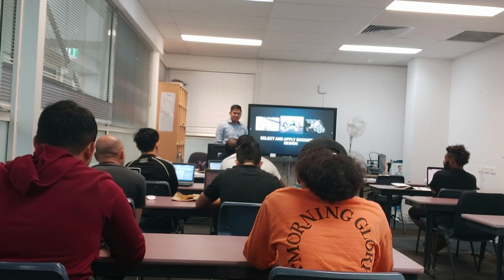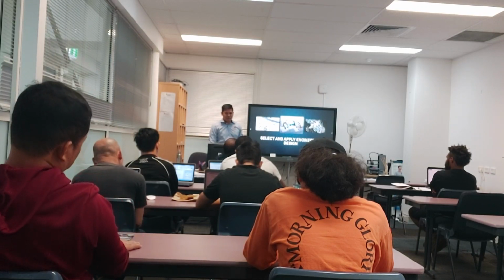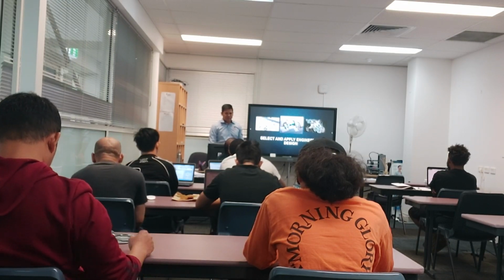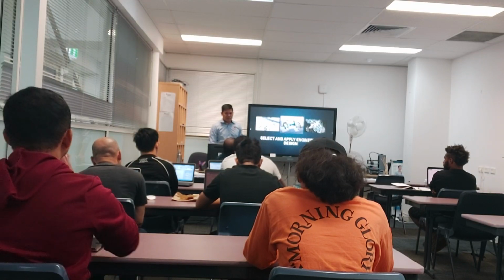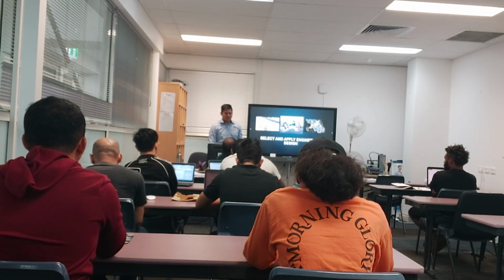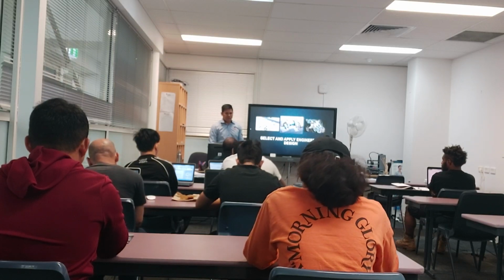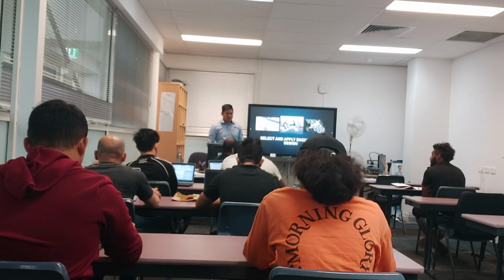You'll be given by the client or the customer or your target group the required final output of any particular machine. Based on that, you have to back calculate. Suppose you want to design a gearbox. You'll be given an input speed, an output speed, and an input power. You need to calculate the output power, and based on that, calculate various shaft diameters and the configuration of the gears inside. That's what is in the design.